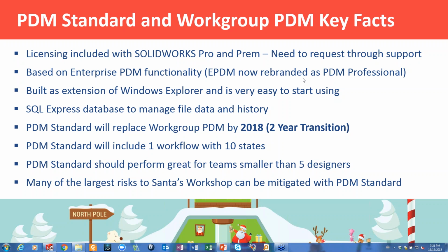was approved for production. So 3 is sometimes all you need, but it's very common for customers to grow that. It depends on how complex your process is, because ideally you have a status for every key part to your process, okay? And it's also very common to have different file types follow different workflows, which is not possible with PDM Standard. The biggest use of that is if you do non-SOLIDWORKS files, such as Office documents, okay?